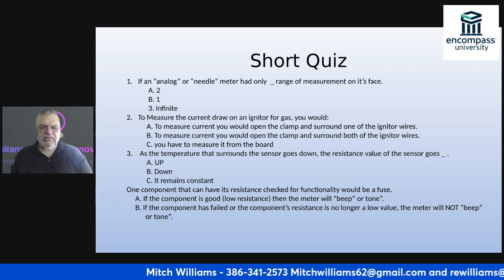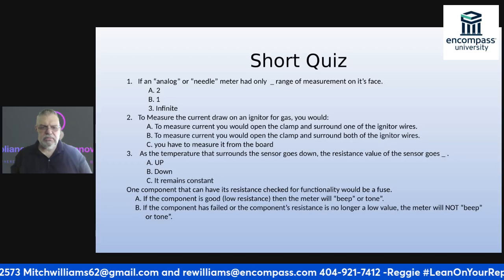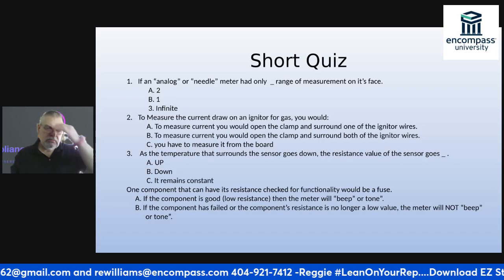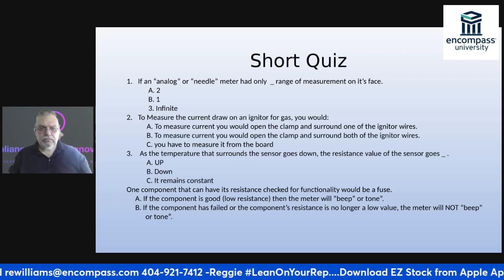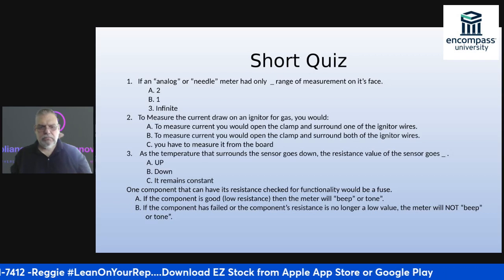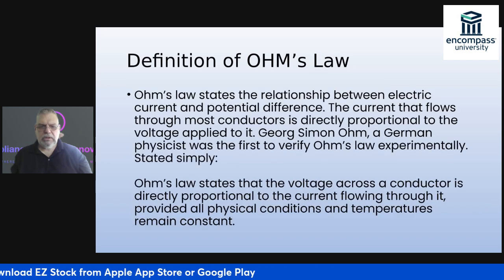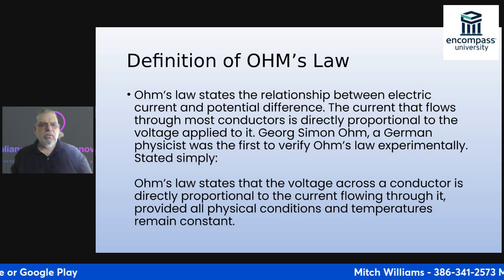If the component has failed, the component resistance is no longer a low value, and the meter will not beep or tone. It won't do anything.